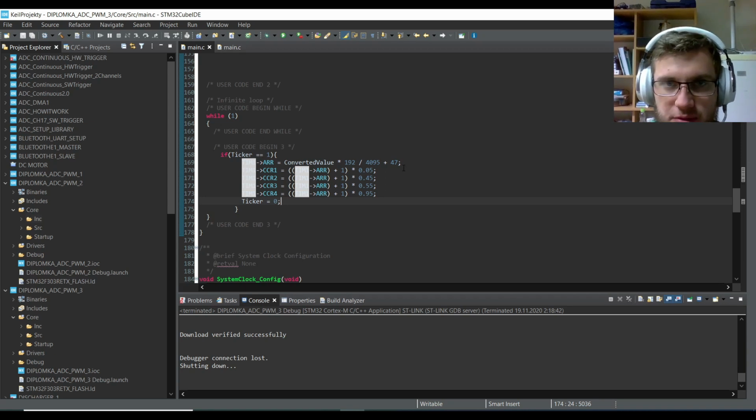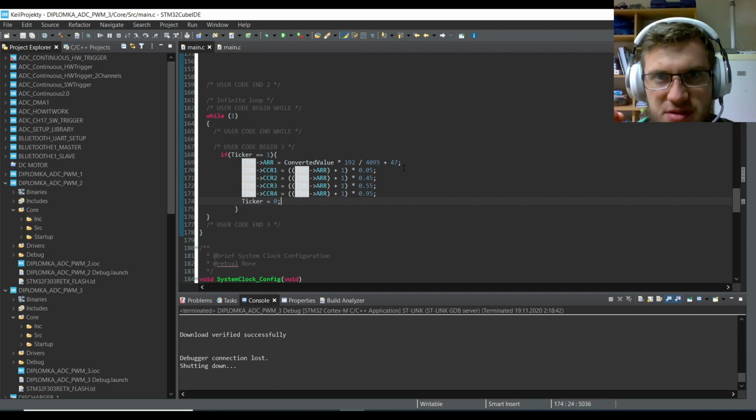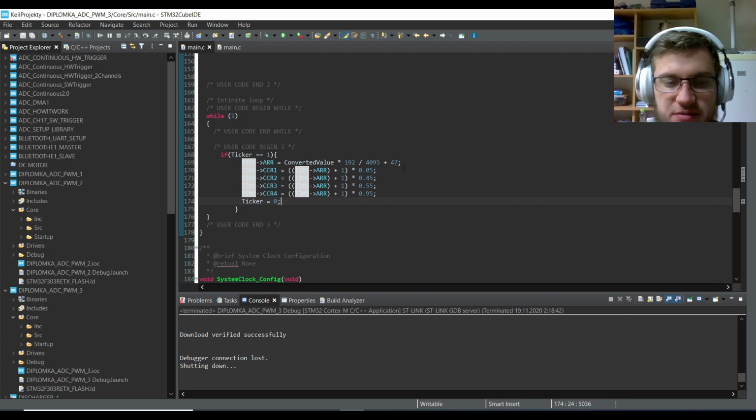As you could see on the video, the PWM is actually not clean, and both of them have the same issue: there are some small spikes where the signal should actually be 0, when the other PWM signal goes from 1 to 0. To be absolutely honest, I don't know what causes it. As you could see, the code is actually quite simple. Maybe it is a hardware issue, which I hope it's not, because these spikes are quite irritating.